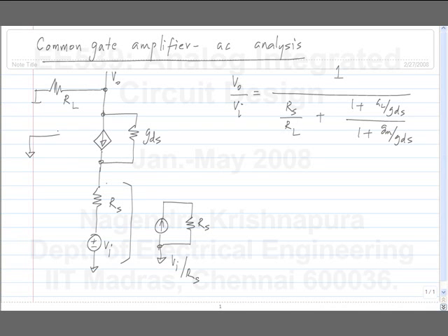Gate source and source to drain. There is no direct capacitance from source to drain in the model of the MOSFET. In very short channel MOSFET, you do get some capacitance between source and drain, but it's typically very small, and most of the time we completely ignore it. There is a channel capacitance between gate and drain, which in saturation region is mostly due to overlap. What else?